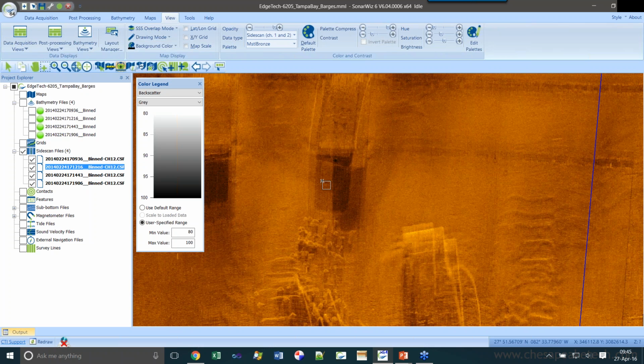And over here you can see where we've got bright data that was imaged into this area and then shadow averaged together. So this area should probably be a uniform or homogeneous sand, but what we see is this big shadow that's cast across there, and that's because the line to the north was shining at such a high grazing angle that there was no data in here, and so you get this dark area. When you use swath bathymetry from a multi-beam echo sounder or from an interferometer, you can avoid these problems.